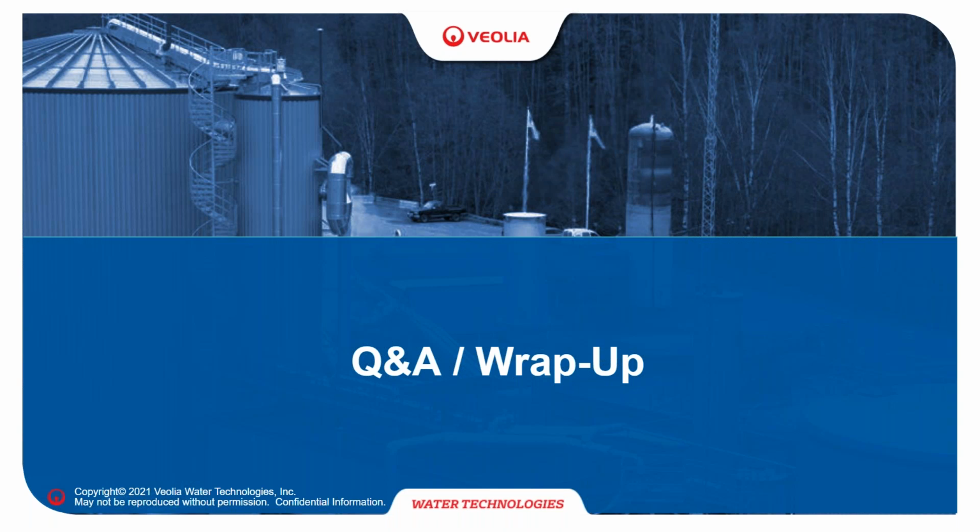That'll give you a good measurement of the percentage of methane in the biogas. Using your total gas flow and the percent methane, you get your methane production, compare that to your COD reduction, and you should get that 0.35. So that's what you need to get good measurements.